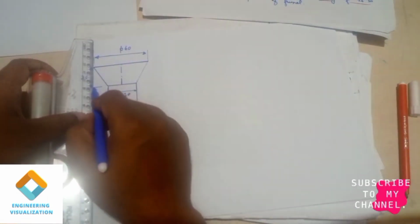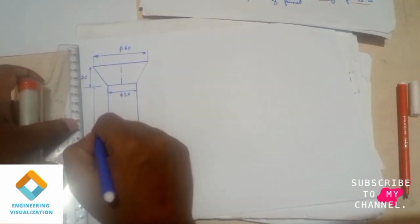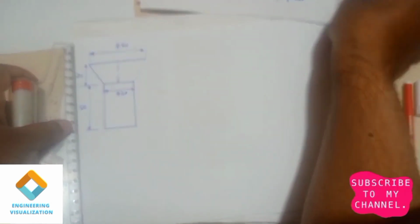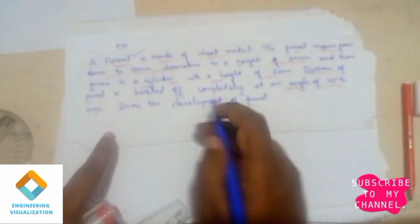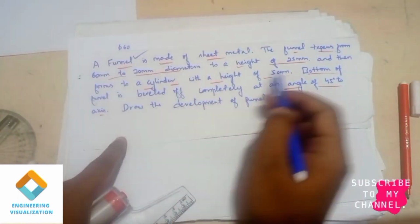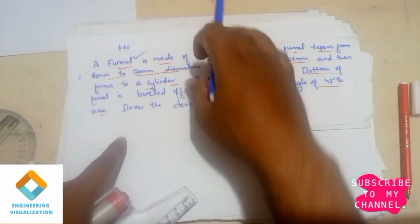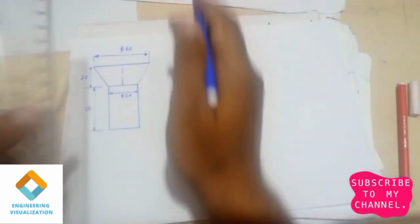We can show the dimension for it. It is 50 mm in length. Now we need to cut this lower part of the cylinder at an angle of 45 degrees. You can see the question: the bottom of the funnel is beveled off completely at an angle of 45 degrees to the axis, that is from one end.